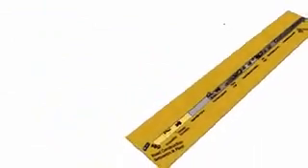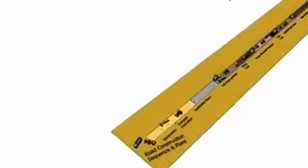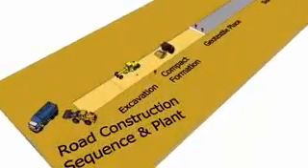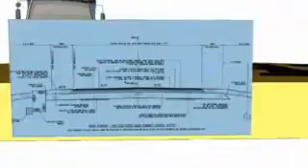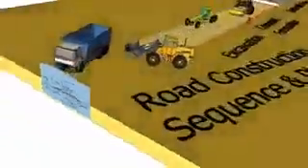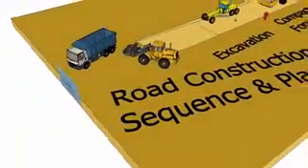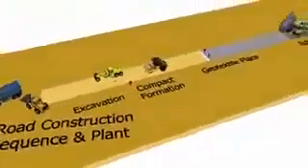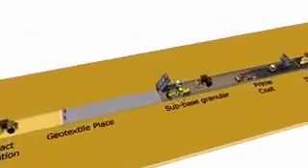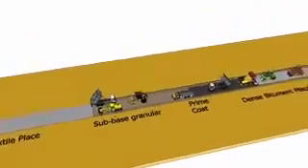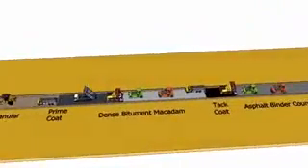Roads, motorways and bridges. Shown is the general construction sequence, methods, and equipment used to build a road: setting out, stripping vegetation, excavation, install underground utilities, granular sub-base, asphalt pavement, road markings, street lights, and signage. Earthworks include excavation, trenches, haulage, grading, backfilling, filling and compaction.